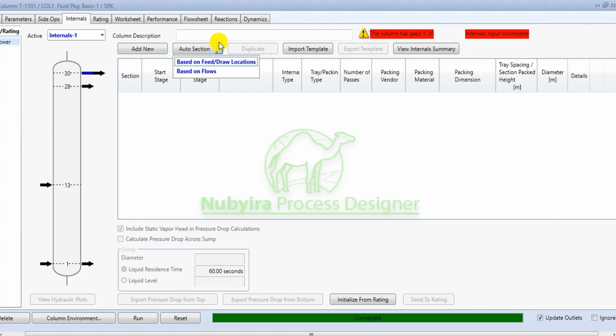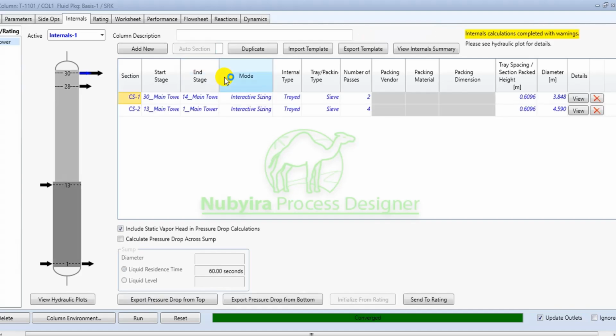You only partition a column design when it is really required, when you can't find another way. If you have a straight run column, it will be very easy to build and manufacture in the yard, so you don't want to create problems for yourself. I'm going to use this, then adjust the sizing when it is done. Even using the flow, it is still partitioning into two.